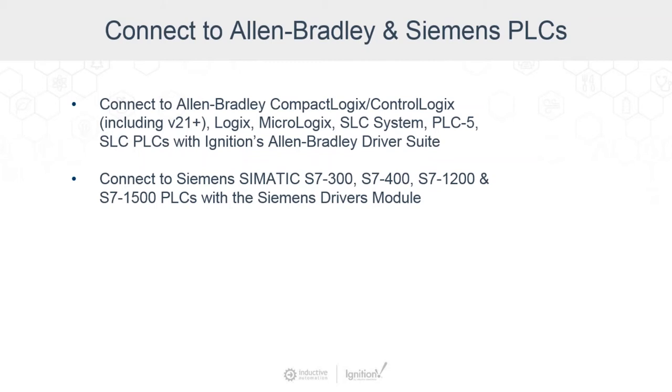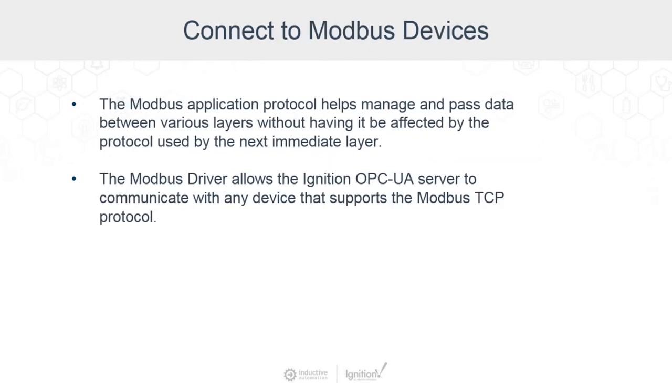In addition to that, if you take a look at Modbus, in case you don't know, it's an application protocol that helps data to be managed and passed between various layers without being affected by the protocol used by the next immediate layer. So Modbus TCP, also known as Modbus TCP/IP, is a simple Modbus protocol running on Ethernet over a TCP interface. The Modbus driver allows the Ignition OPC-UA server to communicate with any device that supports the Modbus TCP protocol. It's a generic, simple driver that allows PLC support.